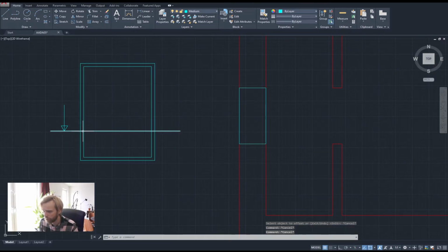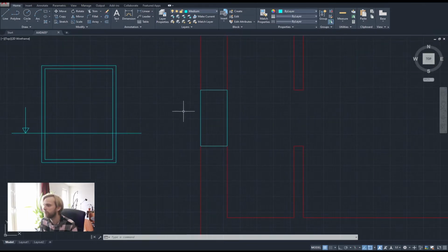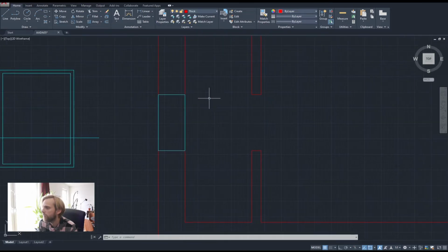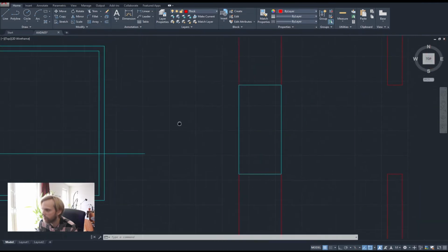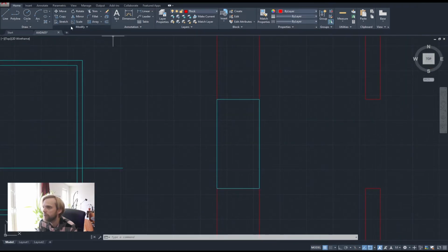So we're going to cut through the frame here, through the glass here, through the frame here. Let's do that. For the window frame, what I prefer to use is 5 by 5 centimeters. It's not accurate, but that is enough for our level of detail. Since we're cutting through the frame, I'm going to be using a thick line, and I'll just draw the cut of a frame anywhere on the screen, it doesn't matter.